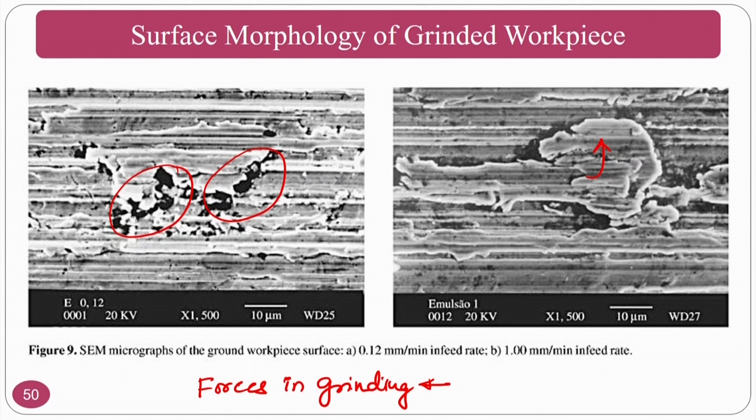All these things are because of the interaction forces of the grinding process or any solid based tool, like the lathe in the turning process, where the forces are also very high. Whenever you talk about the finishing process, your forces should be as minimum as possible, so that the depth of indentation is very small, you can get microchips or nanochips, and you get a good surface finish.